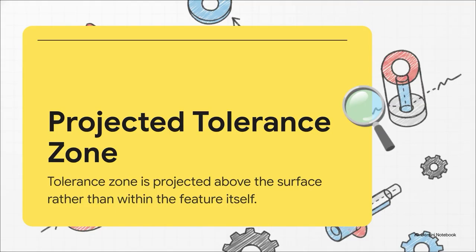So how do we fix this? Well, here is our exact, bulletproof solution for this trap. Straight out of our GD&T symbols reference document, meet the projected tolerance zone symbol. It's a capital P enclosed in a circle. And honestly, when you drop this little symbol into the feature control frame, it does something geometrically profound. It literally extracts the tolerance zone from inside the part's material boundary and projects it outward, right into the air above the surface, extending through the actual height of the engaging fastener.